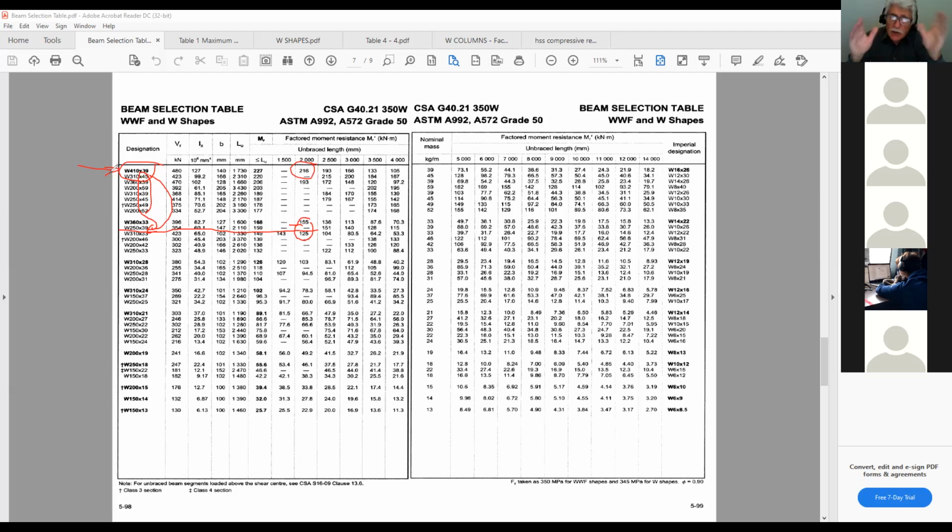And it's not going to be that much of a difference because if you look at IX here, it's 120. Oh yeah, it's going to have a good difference in deflection. So it might have a problem. I don't think you have a problem with your deflection, but if you can put a stiffer member, the better it is.